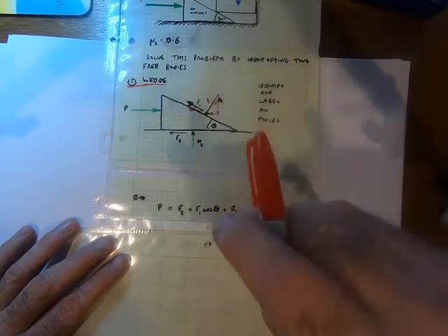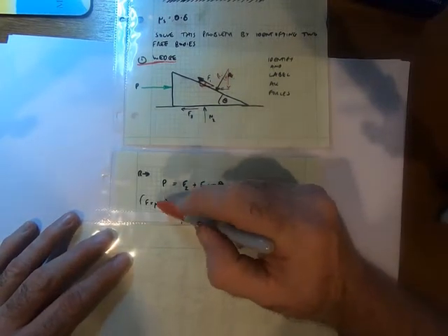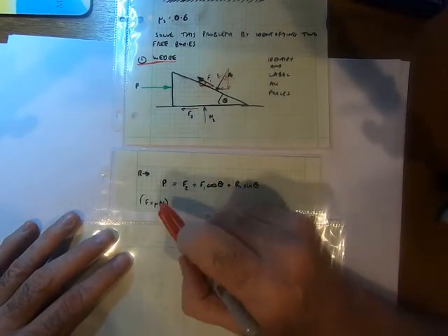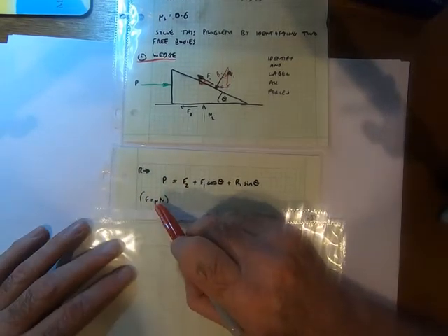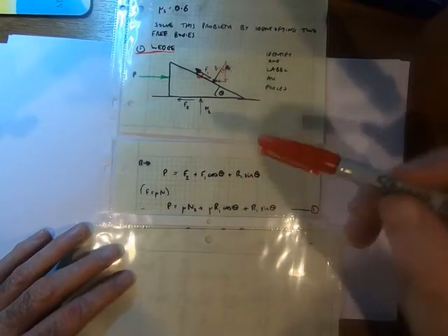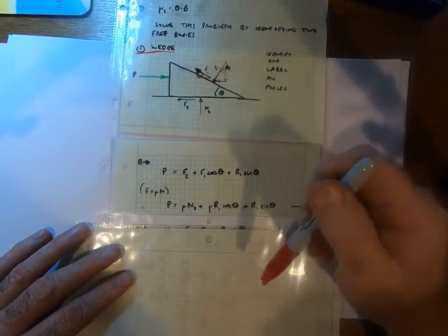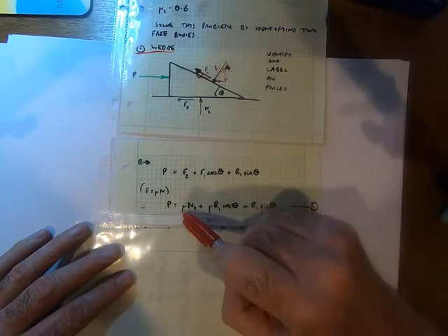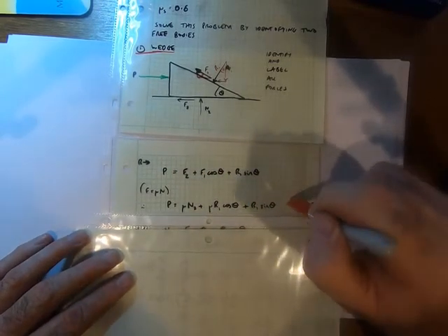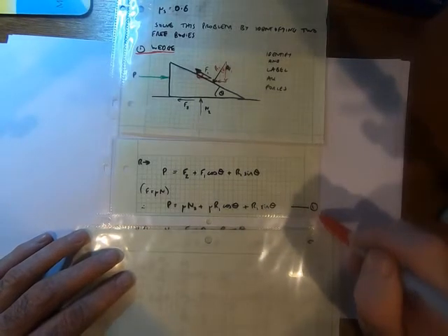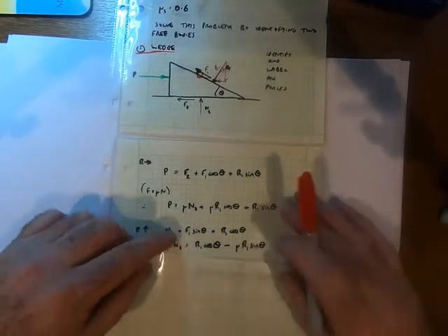So that's my horizontal equation. I do know that F equals mu N: friction equals the friction coefficient times the normal force, by definition. It's a constant of proportionality. So now I can eliminate the friction variables and just work with the reactions. F2 is going to become mu N2, F1 is going to become mu R1. So this equation collapses to equation 1. This is my equation 1 from resolving horizontally. What's next? Well, you guessed it, we're going to resolve vertically.